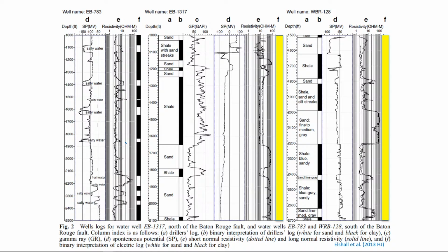So basically, I need to identify these preferential flow paths, because in these preferential flow paths, that's where we will have salt water intrusion. If our study was, for example, remediation, then we have smaller sites, and we might want not just to know that this is sand and clay, we want to know these different types of sand. And you can even get this information from here, because from the shape of this curve, you can even know different types of sand. Okay, so here this is one example.